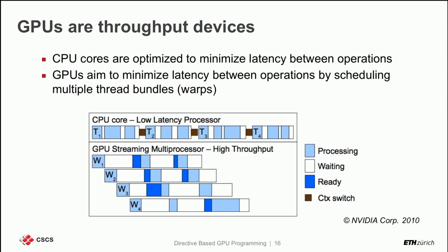So these are the two major ways to cover memory latency, and those are the two different schools, so to say. One is you have very large caches and you expect to fit everything there. The other is to have very small caches but lots of parallelism, and I expect to hide the latency if I have enough work to do. If you don't have enough work to do, then there is a problem.